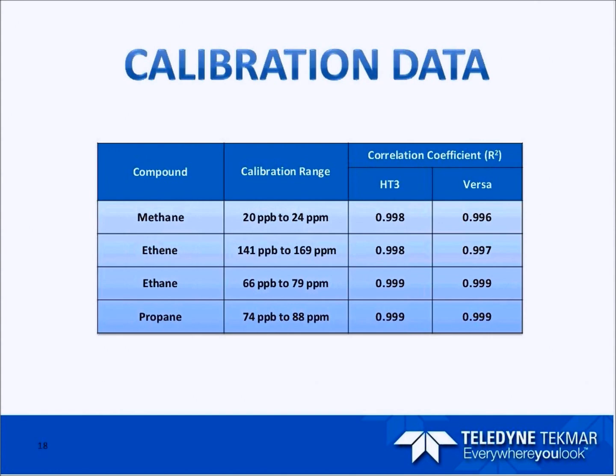And if you look at the range of the calibration, that's potentially 1,000-fold that you're dealing with on dynamic range on this analysis, and that was one of the challenges we had to deal with. That's a really wide range for a gas type analysis, and that's where the FID can definitely be very helpful, because you don't have to deal with a crazy matrix. You're just burning stuff, so it's not as difficult as it would be on maybe a mass spec or something like that. So here's the calibration data, and with that we ran MDLs.